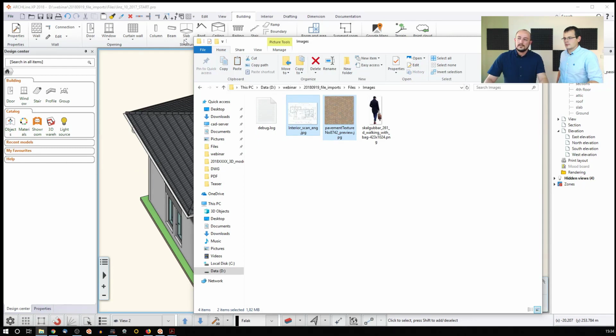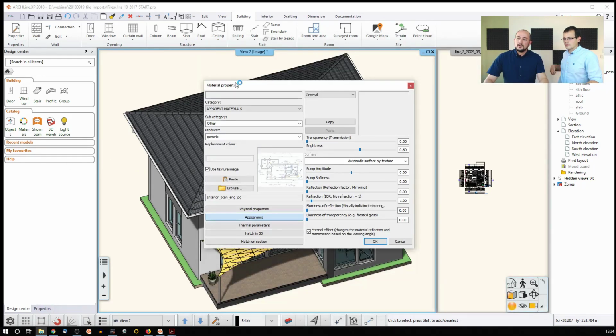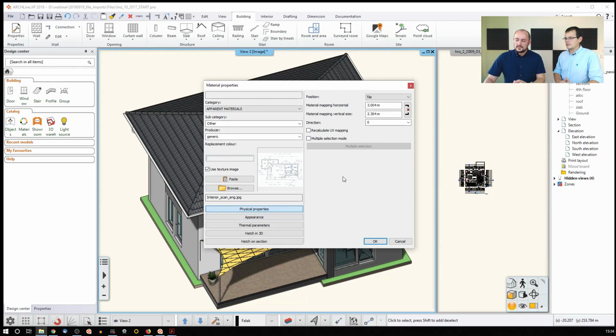I click, drag and release it over here, and the software will give me the opportunity to save all of them with the same settings, with the same size. This comes in handy when you have specific fabric patterns of the same type, and you would like to quickly do the generic settings and then fine tweak them one by one. So you can click and drag and import multiple image files and turn them into materials in one single step.